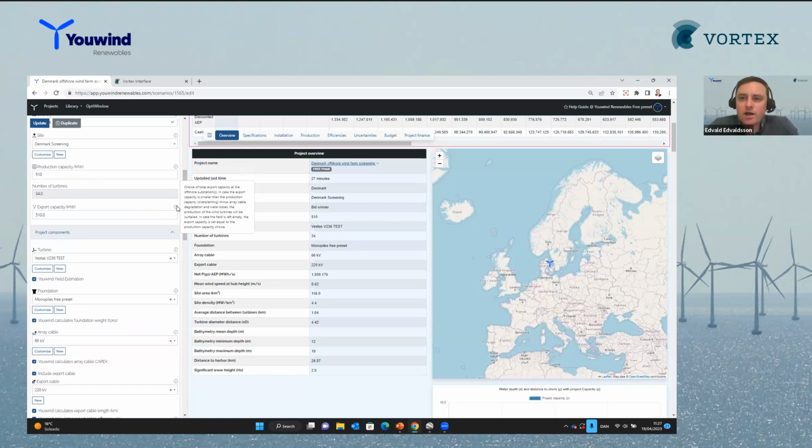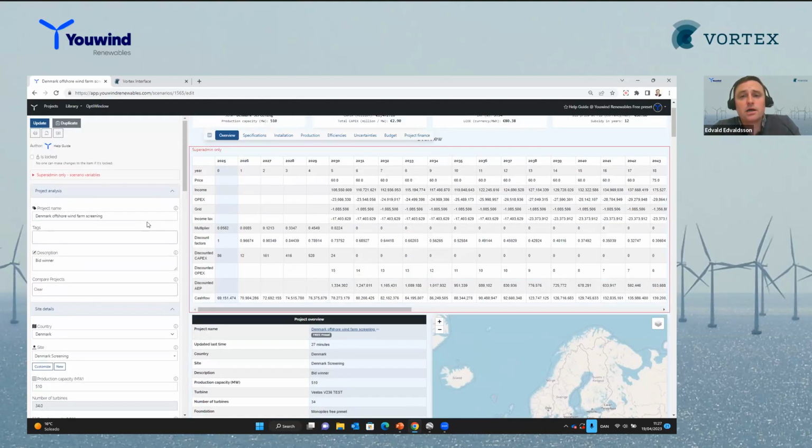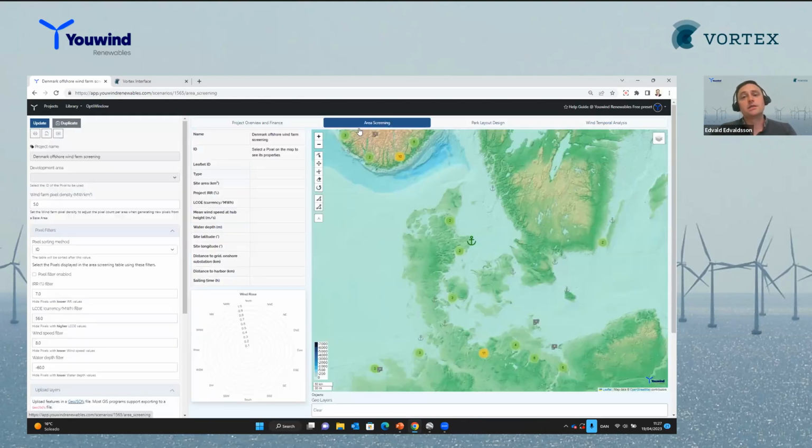So this is a way for the users to see if they would like to install one or two or three more turbines at the location, and to see what sort of other export or curtailment losses there might be appropriate as an output for the particular project. And for very high wind sites, this could be interesting for the overall analysis. For now, we'll keep this as the same, so we're not doing a curtailment or an overplanting scenario here.